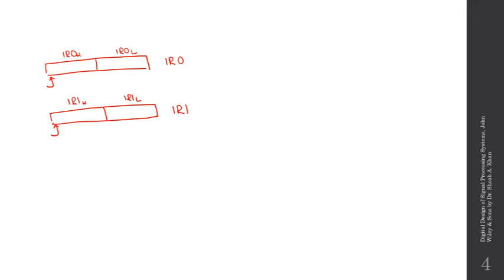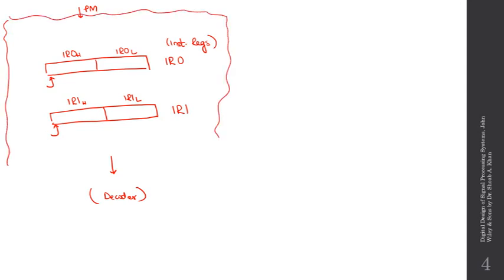So these are essentially the instruction registers. These registers will contain the instruction that is going to be executed next. The data being provided to the instruction will be fetched from the program memory, and the data being provided to the decoder for further processing will be provided by the second instruction register, IR1. This as a whole, which we are going to design in a short while, will be our instruction dispatcher.